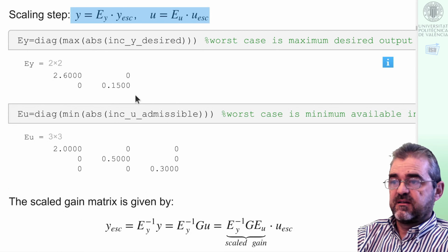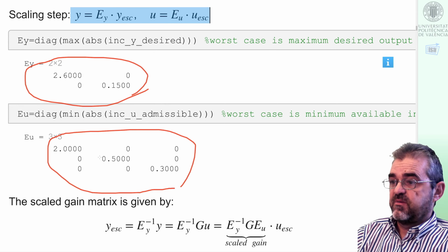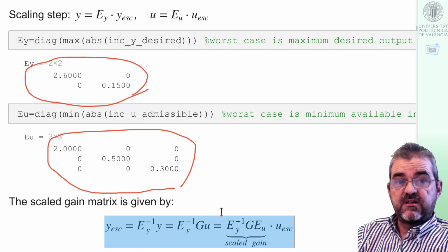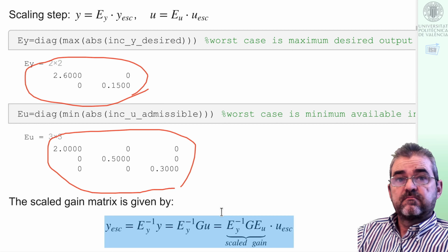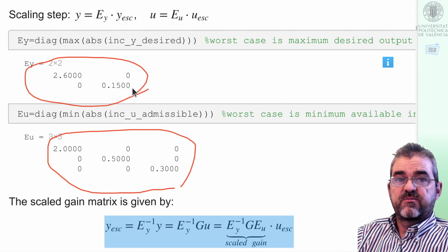So these are the scaling equations and the scaling matrices, and in previous videos we did the change of variable to scaled units just with the DC gain. In here we'll do it with the full G of S, the full frequency response of our systems. For total disturbance rejection, output scaling EY will not be relevant in the computations, but as we are mixing setpoint tracking and total disturbance rejection, we'll keep that scaling in both problems.